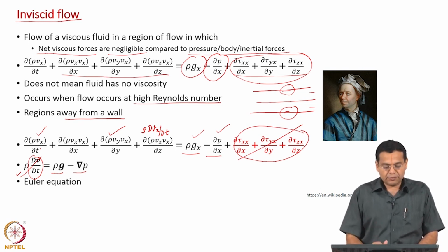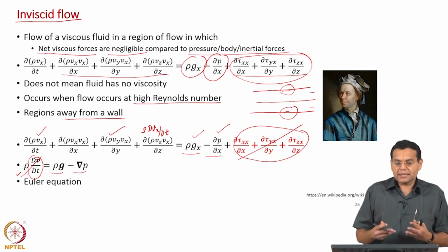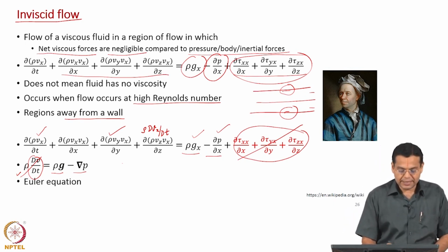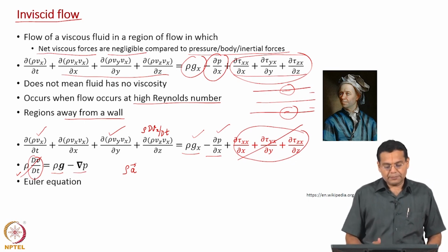Second, when the fluid moved as a rigid body, you had the left hand side, but it was one acceleration term for the entire fluid body. So, on the left hand side we had rho and dV vector by dt represented as A vector, and on the right hand side both the pressure gradient term and the body force.